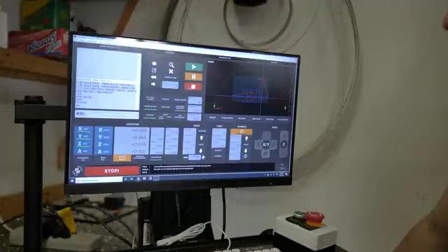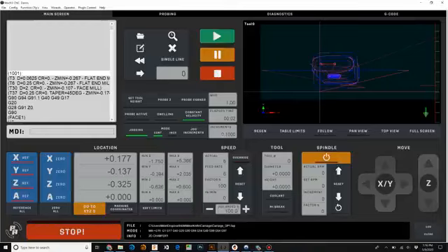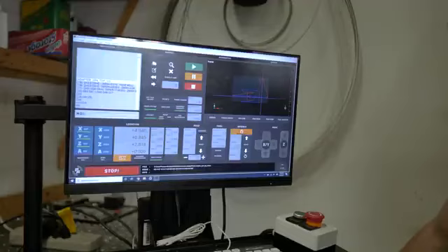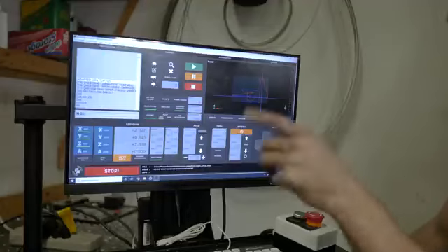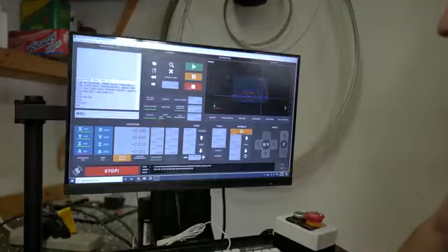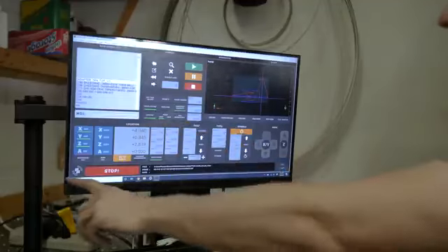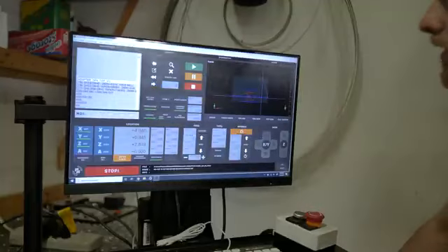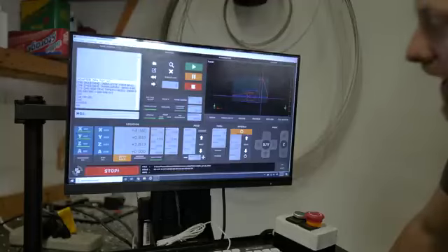So let me kind of walk you through my thinking here. First of all, you might be amazed that Mach 3 supports 16:9. And in fact, it sort of does. You can create the screen set to whatever size you want. Now, if you set it to 1920 by 1080, the standard 16:9 high def monitor resolution, it does some really weird scaling, and it took some experimentation to figure out what its real resolution is, which is basically the full resolution minus the start bar and minus the menu bar on top, plus a tiny bit on the sides that it subtracts as well. But once I figured that out, all the text, all the imagery looks nice and clean.